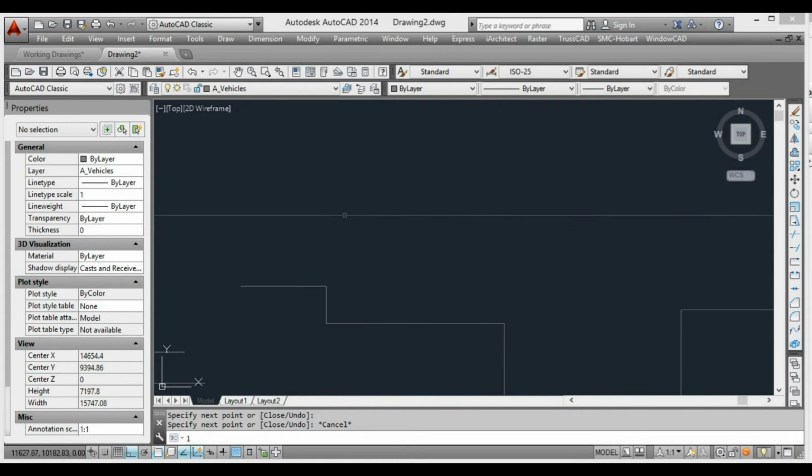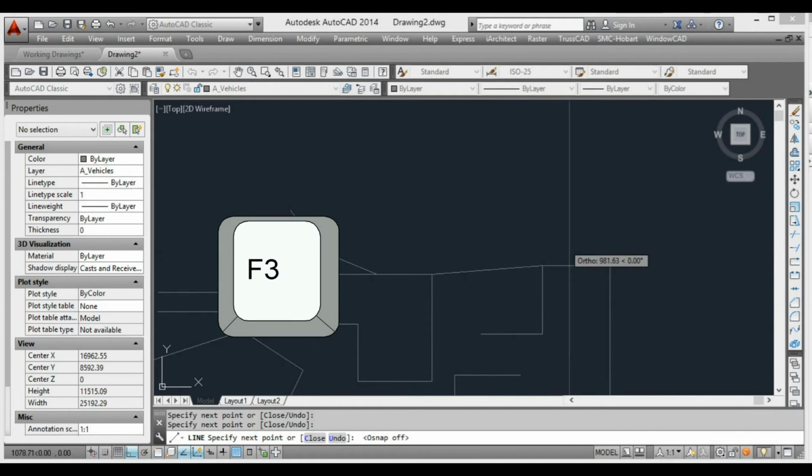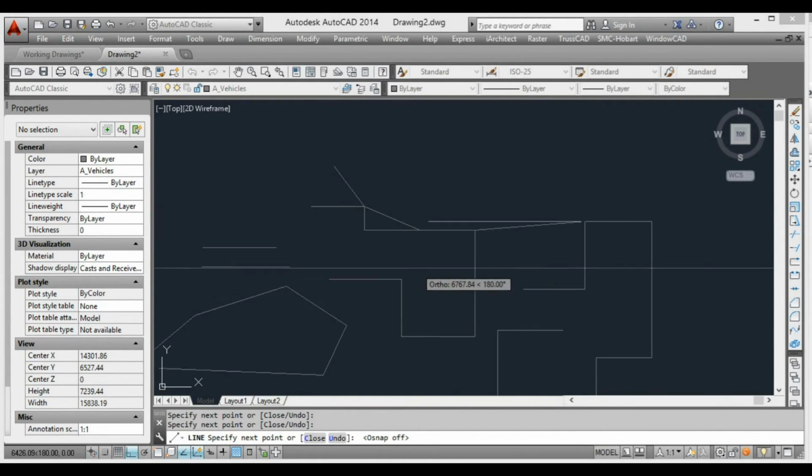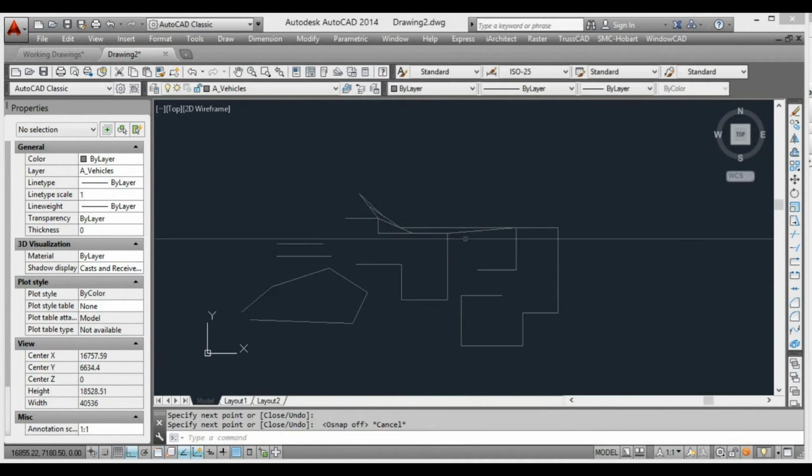The other thing that I didn't mention was the quick way to turn the snapping onto the various lines on and off. As you can see, we're snapping here. I can just press the F3 key on my keyboard, and as you can see now, it's not snapping to anything. That's turned it off, and that can be very useful because sometimes you might want to get to a certain line without it snapping onto something. So I press the F3 key again, and you can see it's wanting to snap to things, which we can just click on. Okay.